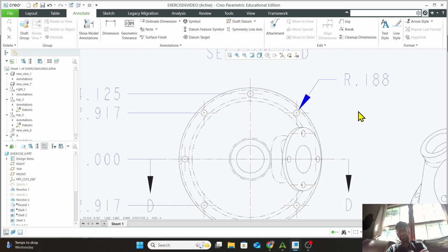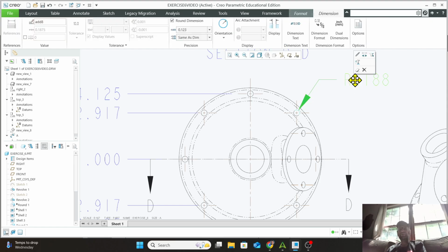Now, when something's being machined, the hole could be made with an end mill. It just depends on the tolerances. But anyway, when I'm specifying a hole, I don't want to do that with the radius. It's always going to be with the diameter, right?